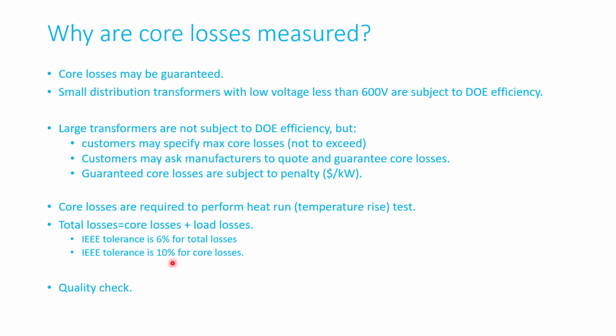you can have a short circuit from lamination to lamination, which will cause circulating current, and it will heat. So that's one thing. The other thing is, the design engineer said this is how many laminations you have to use to build the core. Probably the operator made a mistake and forgot to put the correct number of laminations, so the losses will be a little bit higher.